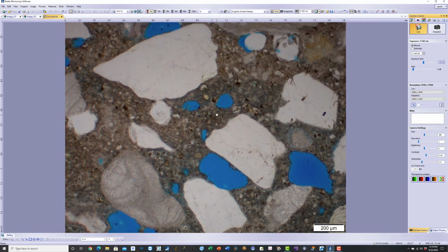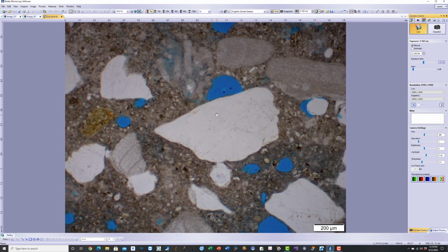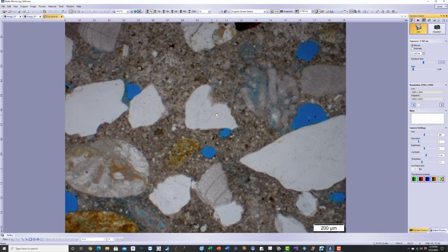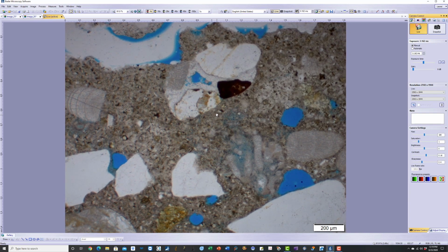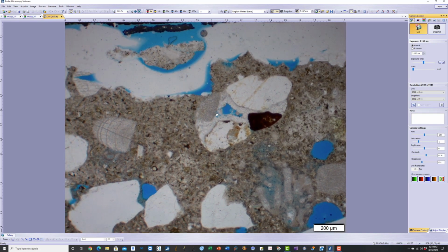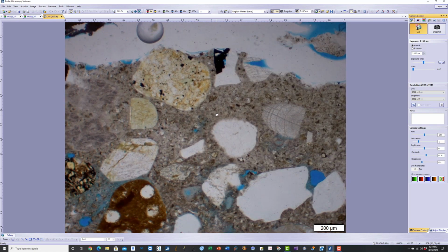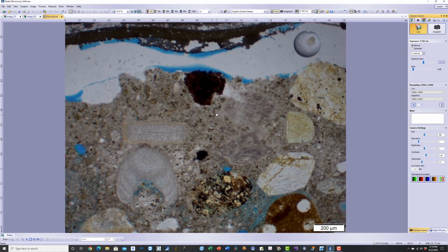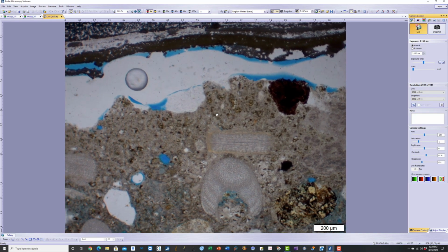The carbonation has increased the density and decreased the porosity because the calcium carbonate product of carbonation takes larger volume than the calcium hydroxide crystals of cement hydration that it replaces. So a smaller volume of calcium hydroxide converts to a larger volume of calcium carbonate, and as a result of the carbonation, paste usually densifies unless the carbonation